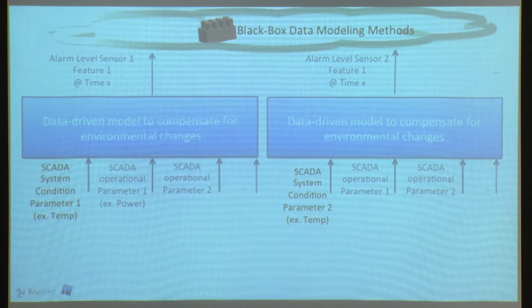Then there's a lot of learning going on slower data. So on the 10-minute values, for example, at temperature, you can model its normal behavior. So you take historical data of a whole set of parameters, for example, the RPM, the power, and so on. You can predict based on the other parameters what the temperature will be. You can learn this with machine learning techniques, and then compare the real temperature to the predicted one.